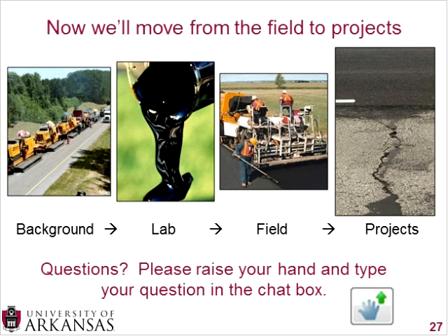And then David asked the question, what is a typical range for air voids in HIR? And I think that depends on what you want as the final air voids. Usually for surface courses, you're aiming for that 96% density, 4% air voids. If you want a slightly tighter mix, you can design for that. Or if you want a slightly more open mix, you can also design for that by adding that virgin aggregate.